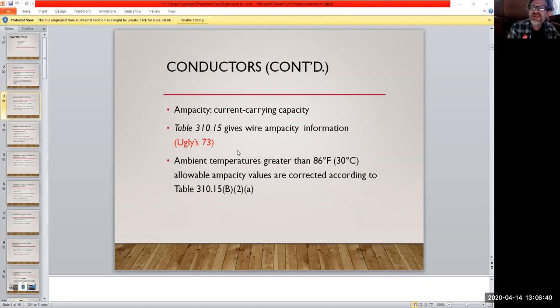And again, you've got to look at your environment, right? So temperature, outside factors, even wet, dry, that kind of thing all come into play. But temperatures are important. And why is that? Well, in some ways, as an electrician, the temperature is not your friend, especially as we get hotter. The hotter we get, the less current we can deliver.